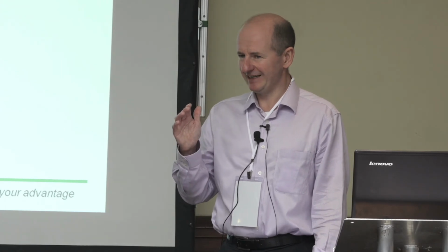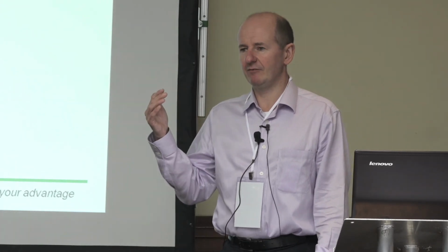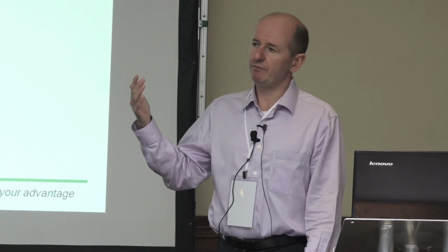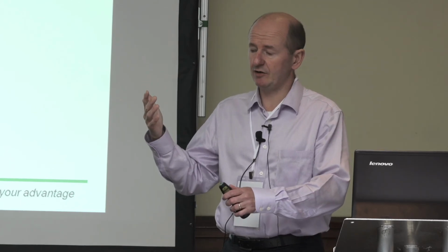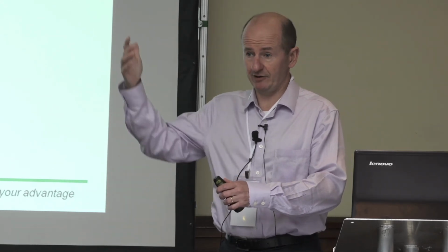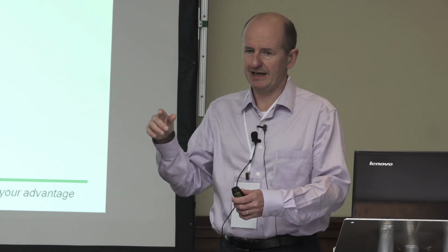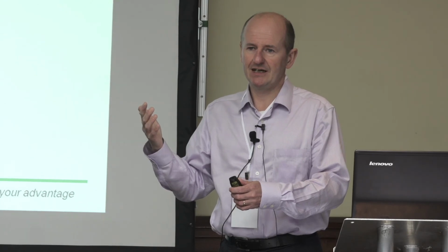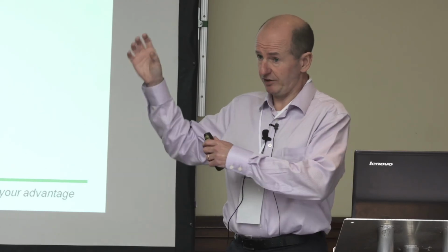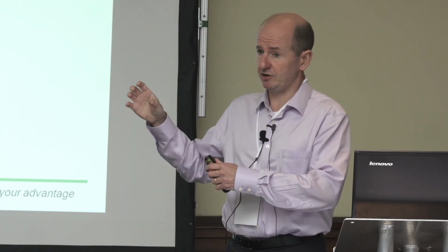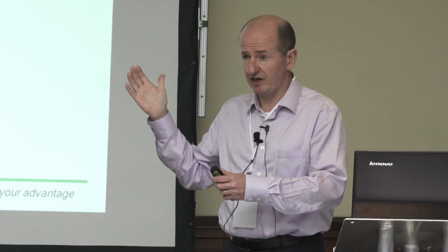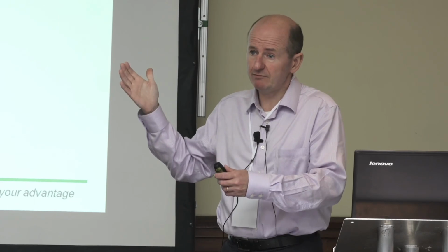And that particular company, I think, who we won't name, have a second generation of their process, which is much improved in that respect. But what it is, to some extent, you can almost think of it as the onset of breakdown, the onset of drain gate breakdown. And you really don't want the transistors to have too high a leakage current. It's a sign of a good process if the leakage current is nice and low. But nevertheless, when you've got a large amount of gate width on the device like that, that output stage could easily, when you're driving it hard, take perhaps 2 milliamps.